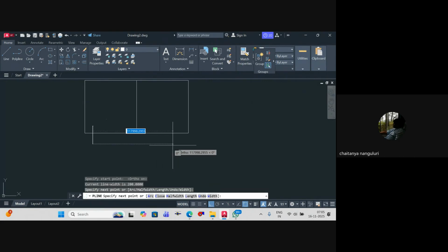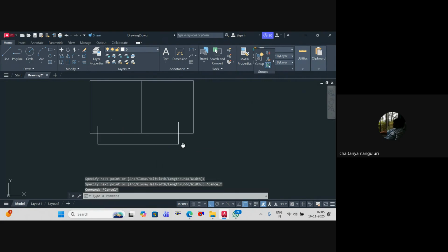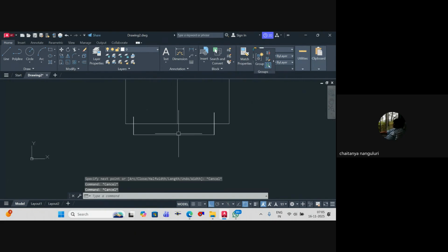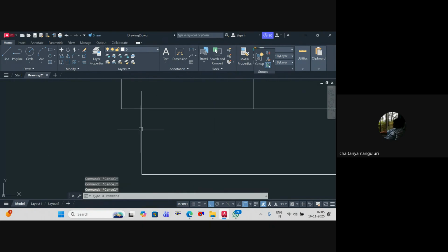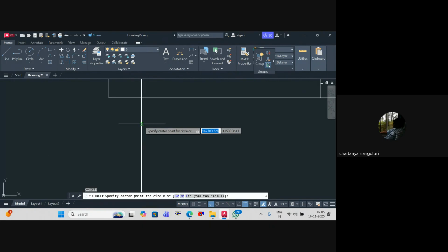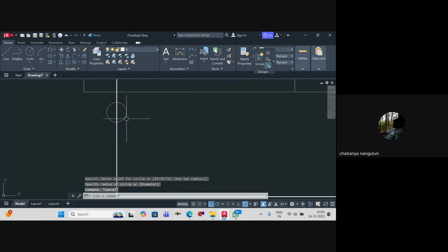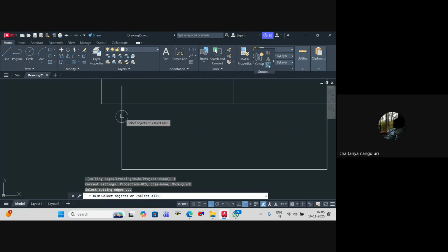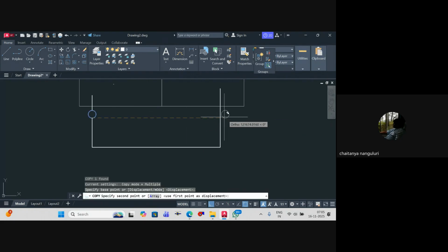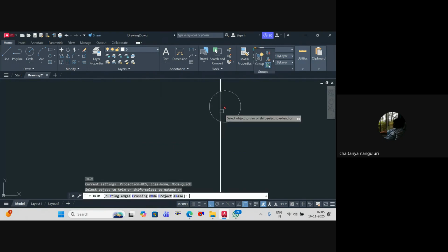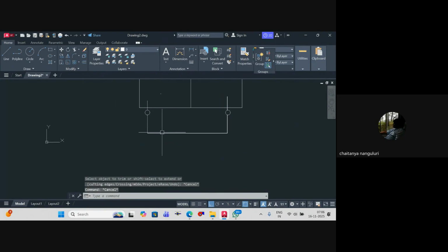You will have your suction manifold, which is common to both the pumps, right? When you connect the suction manifold to both the pumps, here you'll have a strainer. It's up to you, for every pump also you can place it, or directly at these two manifolds you can place your strainer. Nothing wrong with that. Understood? So you can have a strainer at this location, and at this location also you can have your strainer. And then you have a sluice valve or isolation valve.